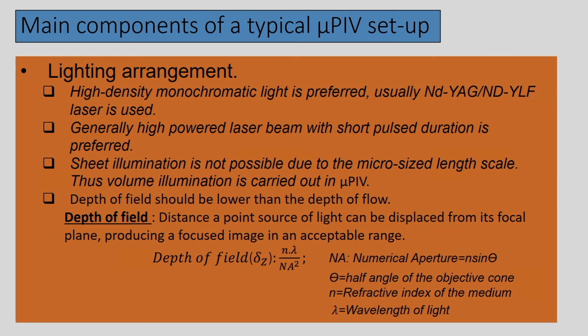The calculation of flow velocity or flow parameters will be erroneous. Why? Because the particles are there in the microfluidic channel, the confinement, which is very small and narrow, so the zone itself is very small. If the light source focuses on a little bit larger area, then the calculation may not be the correct one.